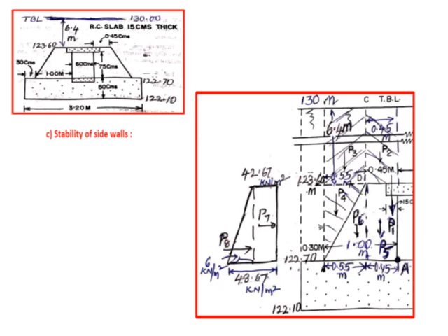As for the weight of the fill, we have calculated the dead load. So from the dead load, the span is 0.9 meters. WL by 2 will give the reaction. So that reaction, the slab as well as the weight of the fill, is transferred as reactions, which is P1, which is WL by 2.